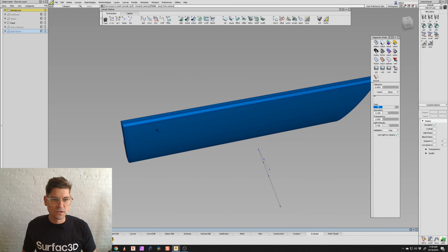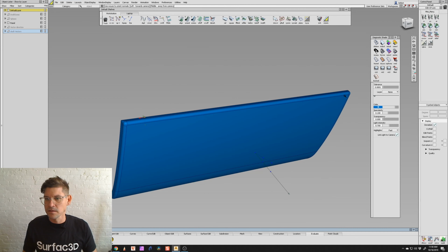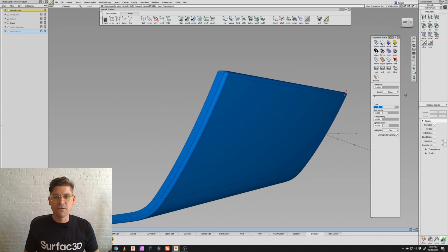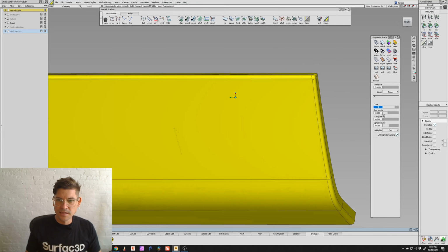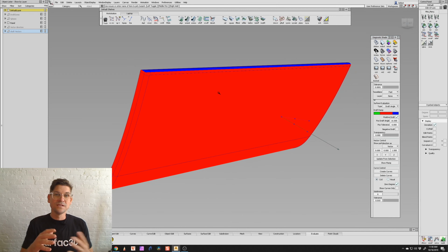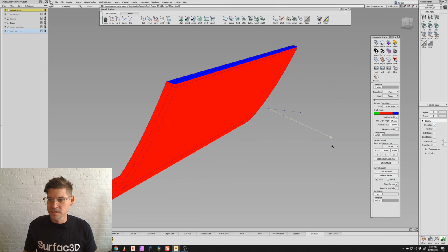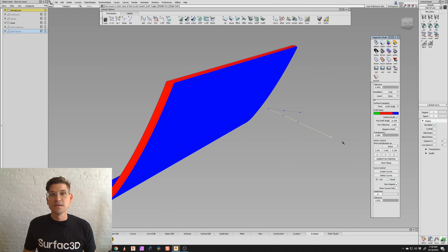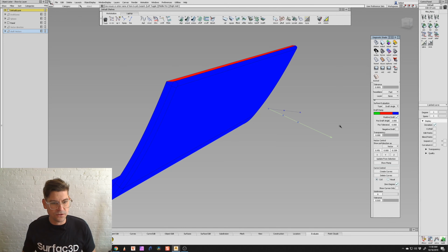So in this case, I'm just going to bounding box with my left mouse button to make sure everything is highlighting in blue and the inside is all yellow. Now when I go back to the tool, we don't see the checkered pattern that showed that some of those surfaces were flipped around. We want to use this vector, so I'm going to select it and say Update from Selection. Since we know we want 3 degrees of draft, or at least it has to pass a 3-degree draft test, I'm going to select 3.